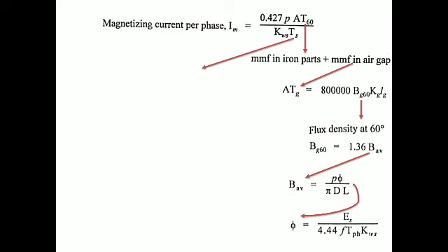to find the T_s value, which means the stator turns. It is calculated by using the conductors, because in the given data we have a Z value. So using Z and slots divided by 60. I think all the data are there. We can directly predict the value of T_s. Then we get T_ph. So from the phi value we got the T_ph value. So one is okay. Then one more data, K_ws, you need to find.